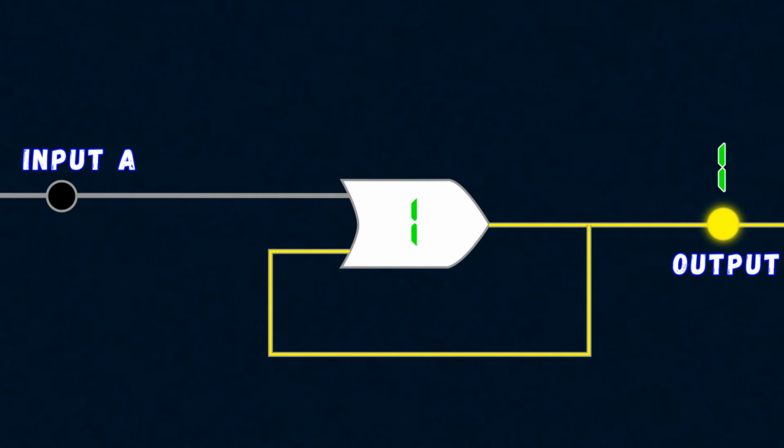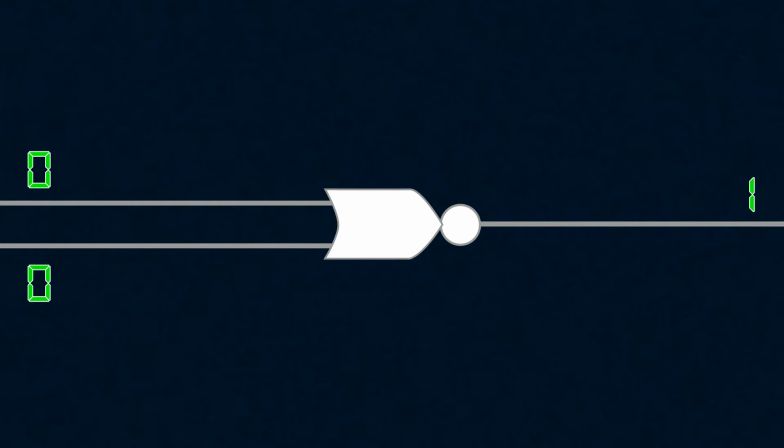There are several ways to do this, and here we will consider only one of them. For this, we already need two OR gates, each consisting, I remind you, of two transistors, as well as two NOT gates, with one transistor each, connected to each of the OR gates. I remind you that the combination of an OR gate and a NOT gate is called an OR-NOT gate, and its result will be exactly the opposite of the result of the OR gate operation. It will output 1 if both of its inputs are 0 and 0 in all other cases.